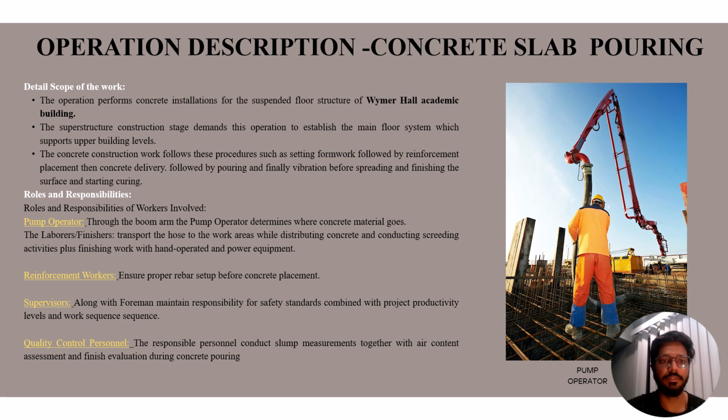Talking about the roles and responsibilities for everyone, there are many workers involved, like a pump operator. He used a boom arm to direct the concrete, and the laborers and finishers, including myself, handled the hose, spreading the concrete and conducting screeding activities, plus finishing by hand. The reinforcement workers prepared the rebar, and then that rebar cage was placed on the slab, using manual and powered tools to ensure that the rebar has been placed perfectly on the slab.